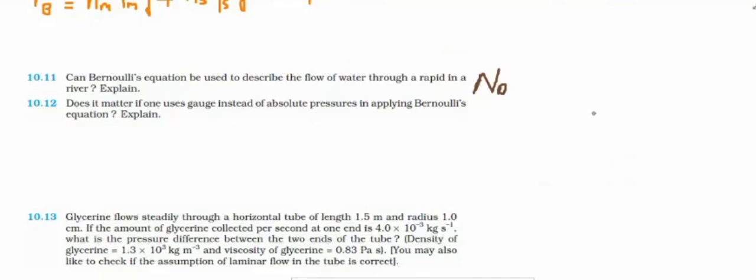You know that when we consider gauge pressure, we will just neglect the atmospheric pressure. Suppose we apply Bernoulli's theorem for a pipe like this. You can see both these cross sections almost at the same vertical height. So pressure at this point is the pressure of liquid plus atmospheric pressure, P2 plus PA, and here also pressure of liquid plus atmospheric pressure, P1 plus PA.